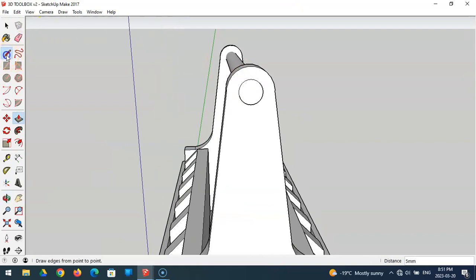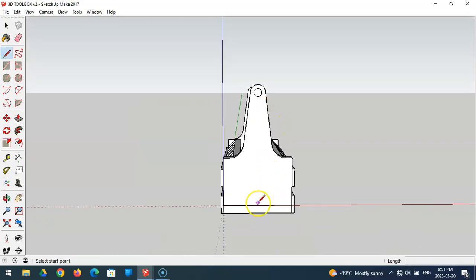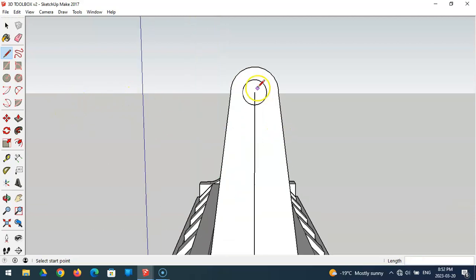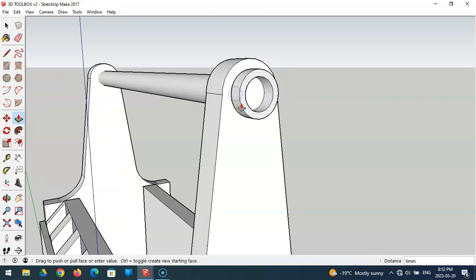So I don't think, no, won't let me find that center. So I got to find that center all over again. So from the middle, 292 up. There we go. Zoom in, grab the circle tool, 14 radius, and delete this line, and this line, and pull this 5mm, and this one as well, just on face.